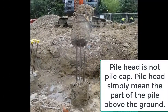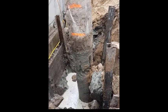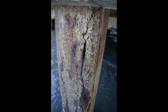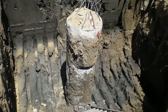So you need to verify the integrity of a pile before we can construct the superstructure on it. So what we mean by integrity is, is there no crack? Is there no bulging? Is there no necking? Is there no void in it? That's what we mean by integrity. So to now test if this integrity of the pile is intact, we need to take a pile integrity test.